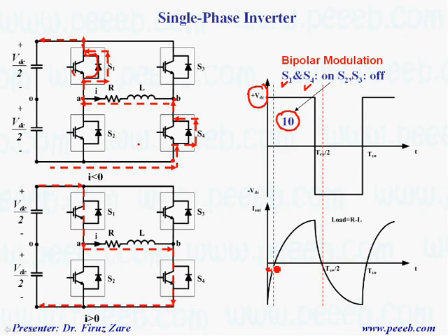And once the current becomes positive, because the direction has changed, the IGBT is turned on, and now it can handle the current. So the current passes through the IGBT, the switch inside the main switch, and the current is positive. That means this IGBT also can handle the current. So that's why for this period, when the current is positive, current passes through these switches.